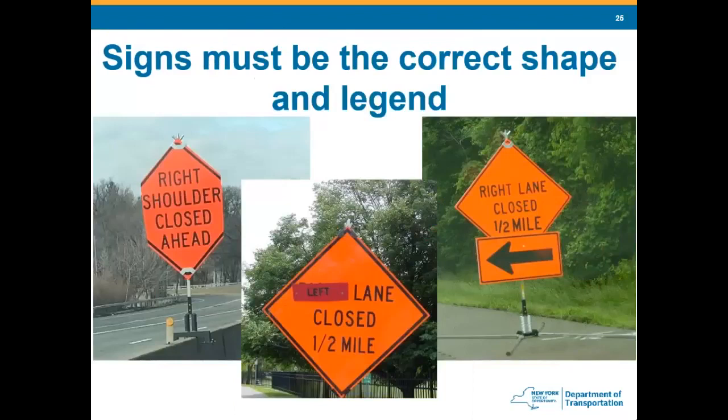If you're going to have an issue like this where it's on the median barrier, you have to use either the smaller sign or a rectangular sign. If you've got these type of signs, the font needs to match and the color needs to match, and they need to adhere really well, and this is just not acceptable. We can't have them stacked on top of the other.